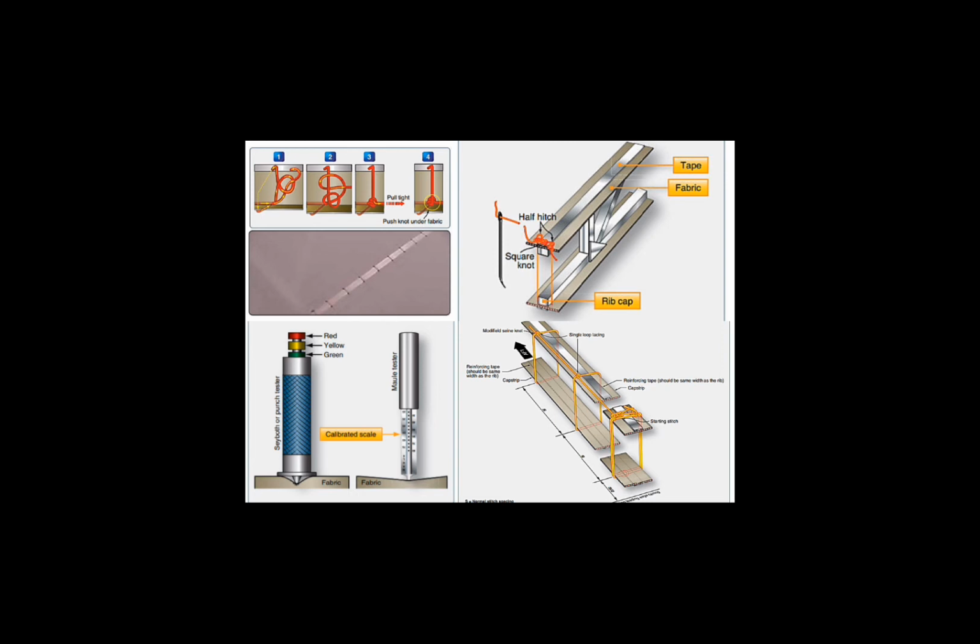What type of machine-sewed seams are used in aircraft covering? Plain overlap, folded fell, French fell. What should be done with structure that will come in contact with doped fabric? Protect with aluminum foil, dope-proof paint, or cellulose tape.